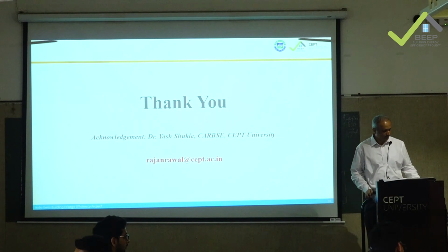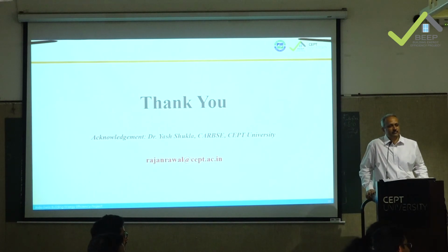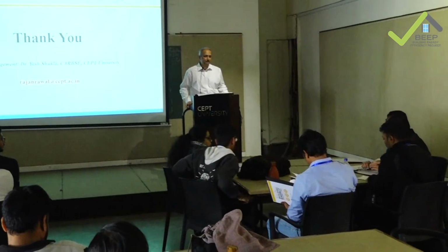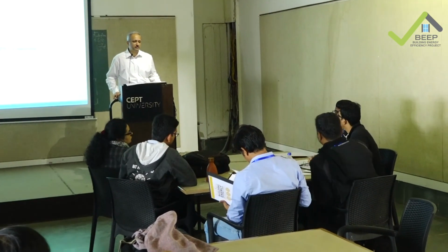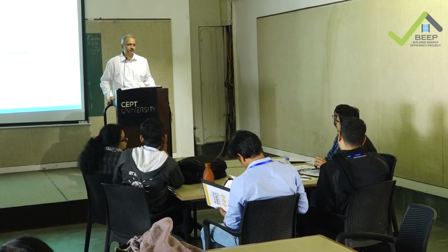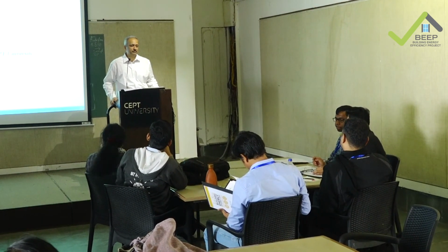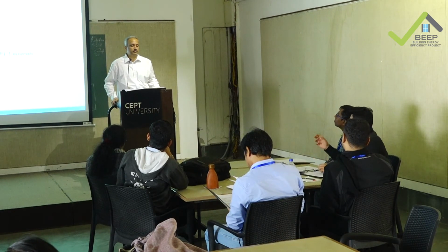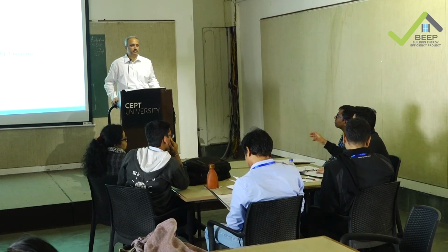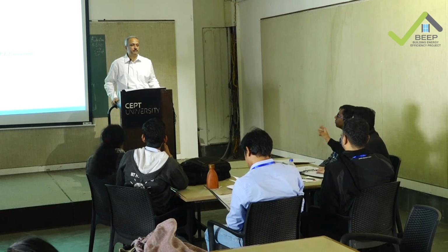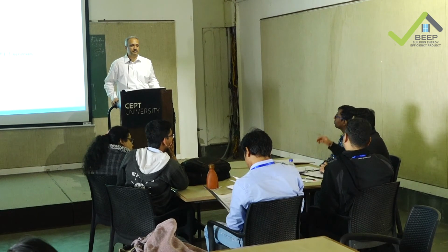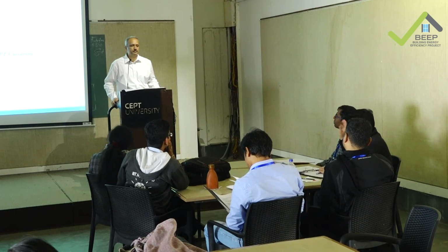So you mentioned the U value, SHGC and VLT for the windows. In general context, U value becomes a direct parameter and these two become indirect because they change according to the U value? No. So my question is, let's say you choose the U value for your window. You want a certain U value. Do you get SHGC and VLT related to that U value? Or can you change that as well? You can change that.